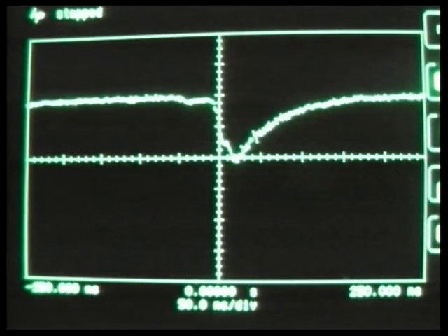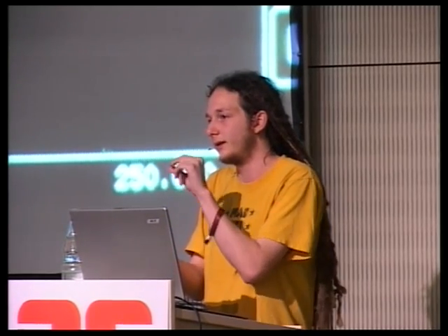So I was wondering if you could do it just with a cap from an I/O pin on the MSP430 going into the rail, just have a falling edge on the other side of the cap. You can. In this case, I used the muxes so that I could switch to a particular voltage. So I can add a capacitor to a test point on my board, get the capacitor at the value that I want to glitch with, and then flip everything over.